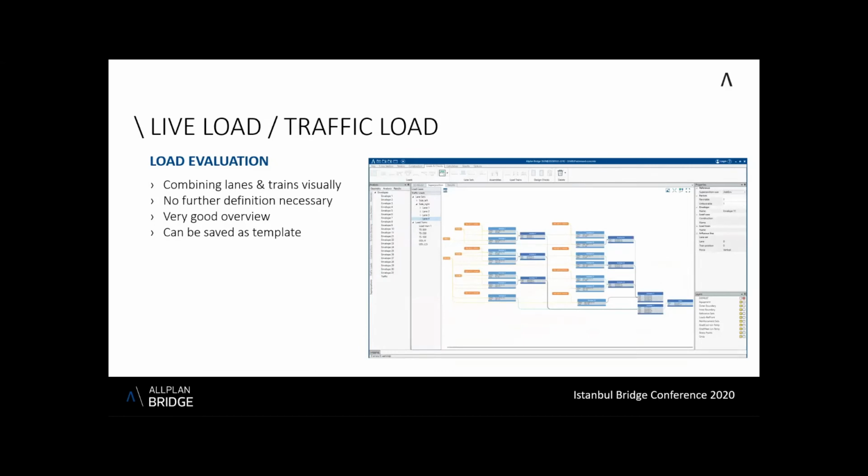In the next step, the most unfavorable influence is determined by integrating the load intensity along the lane, actually along the sections with unfavorable influence in case of distributed load. In case of individual vehicles with point load, the influences are multiplied by the vehicle load or axle load respectively. In this step, also the resulting effects of individual lanes are combined with each other and in accordance with the respective code.